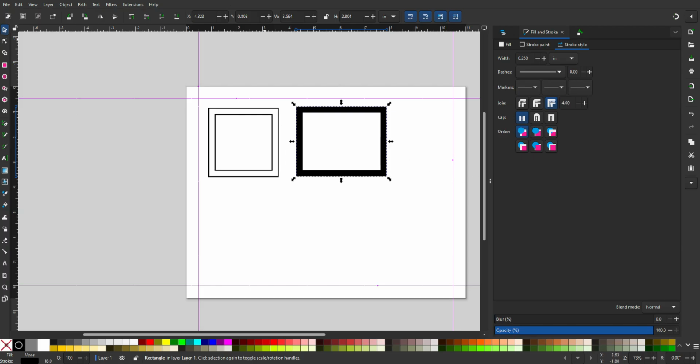So the rectangle object, if I apply path, stroke to path, I'll get this. This has one vector line, whereas this has two, so if I change the vector line thickness, it changes both of those. So if I just wanted to etch this into the surface, if I just wanted to draw on my surface, you want to do the right one. Whereas if I wanted it to cut, to cut the left, and cut, yep.